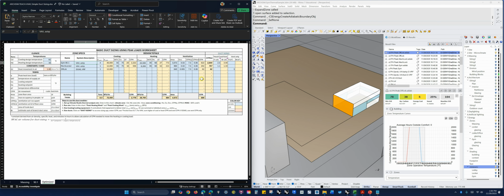So what's going on there? For the first two zones where I'm using VAVs, I'm doing the same thing, just sizing them based on the totals. But for the third zone, why do I have this tiny amount and nothing for heating and cooling? Actually, that's wrong. I should have the heating and cooling totals, because I want to know the size of the system.